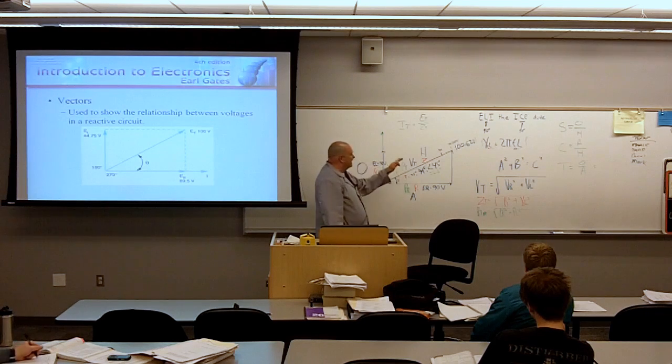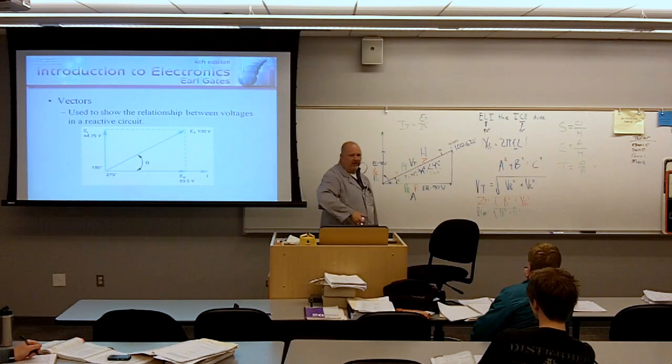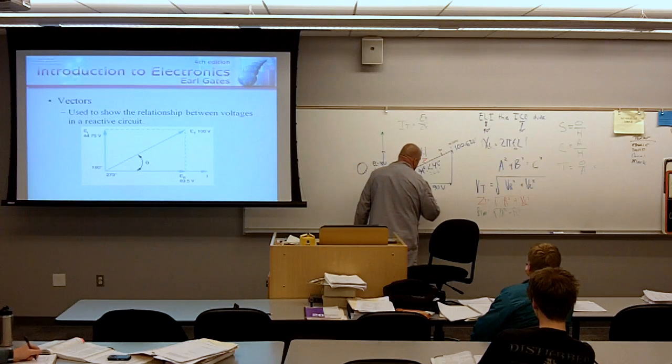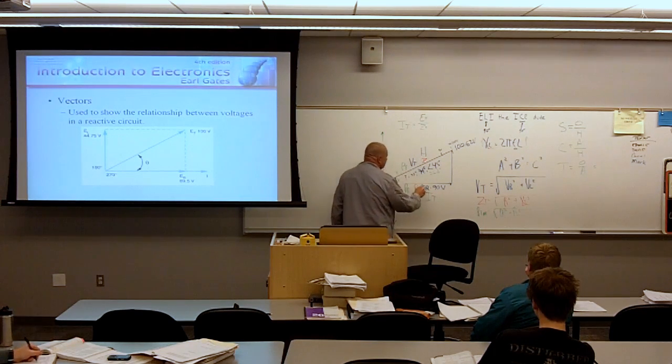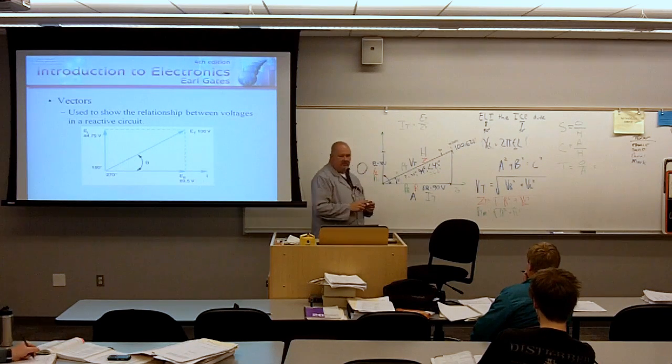And where would I plot that out on my vectorial plot? Where would I get plotted? Down the bottom? Where? On the same vector as what? Resistance. Absolutely. Why? Because resistance is in phase with current. And total current is total current. Whatever's happening at one point is happening at the other point. There's no phase shift of current in the circuit, from any point in a series circuit. So IT is going to get plotted out on this vector. Does that make sense?